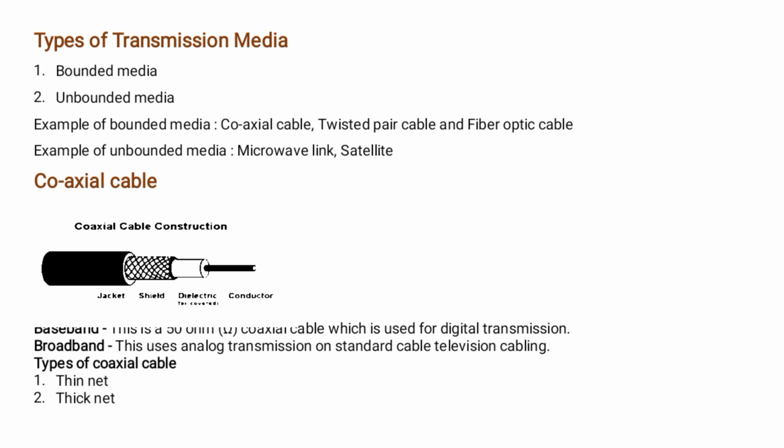Now first we discuss coaxial cable. The figure shows a coaxial cable. Coaxial is called by this name because it contains two conductors that are parallel to each other. Copper is used as the center conductor, which can be solid wire or stranded. It is supported by PVC insulation, a sheath which is encased in an outer conductor of metal foil, braid or both. The outer metallic wrapping is used as a shield against noise and as the second conductor which completes the circuit.